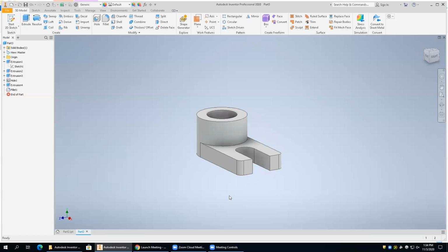So there are a lot of really cool tools. You can either place them after the fact or do them within the sketch. So the idea, guys, remember, is keep your sketches simple, and you can apply some of this stuff after the fact. Whether, for holes, you choose to draw a circle and then extrude it, or you choose to draw the hole tool, that's up to you. The hole tool is probably a little bit more efficient, but it takes a little getting used to. So it just depends on what you do. You're going to be doing this a lot, so you'll see how this works.